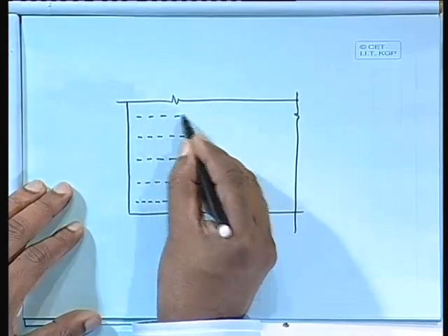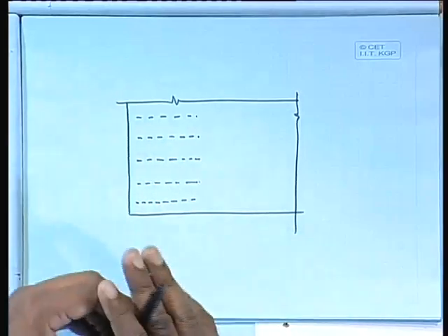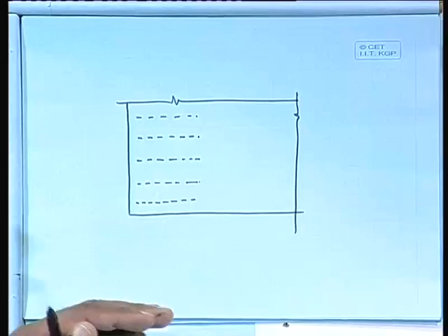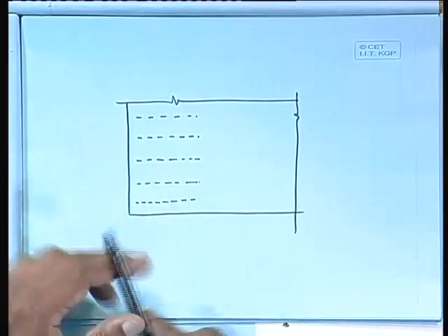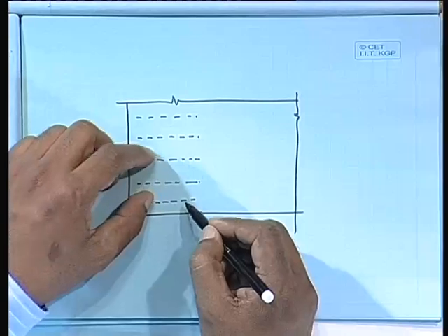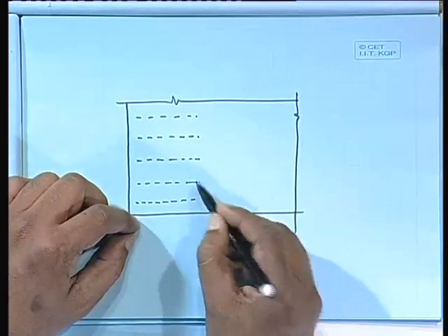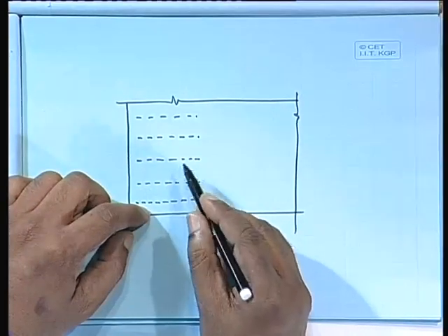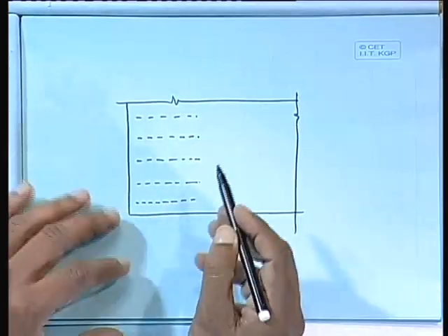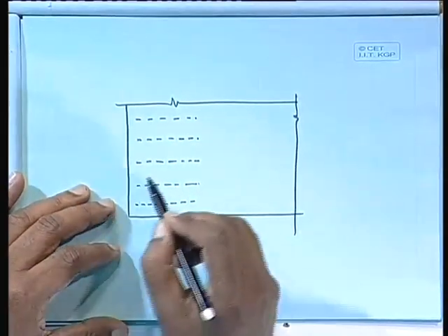We do not go for that crank nowadays, and that way it is easy also. The top bars have separate spacing. Otherwise, for detailing, since you are doing that alternate crank, if it is a 250 millimeter spacing, alternate crank means 125, all those things you have to make. So, the spacing is dependent on the top bars also.